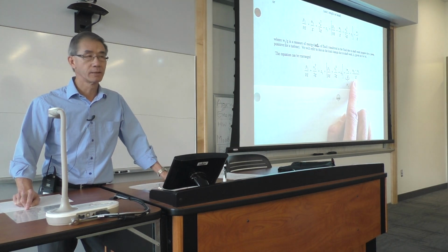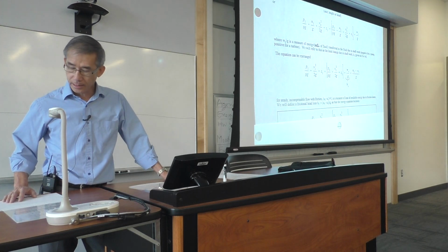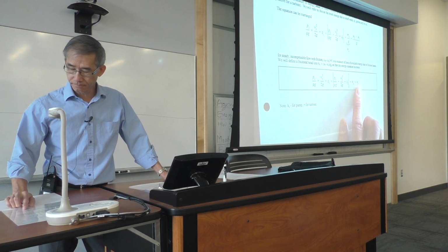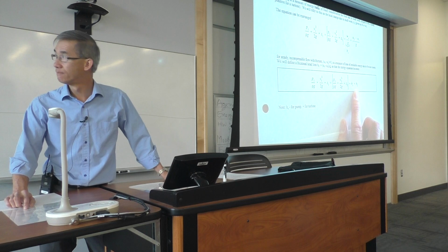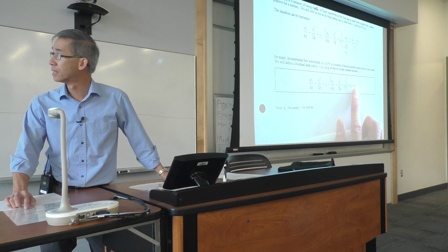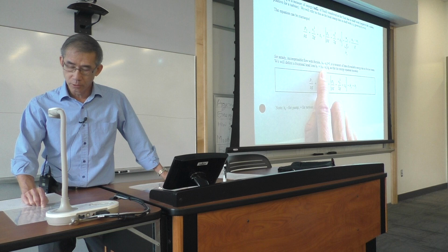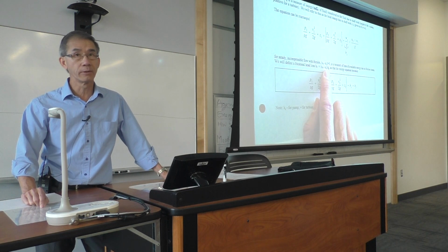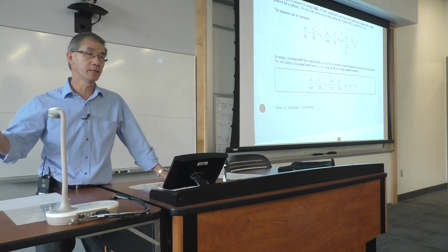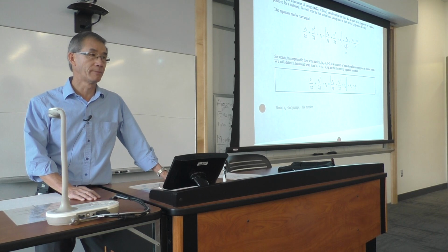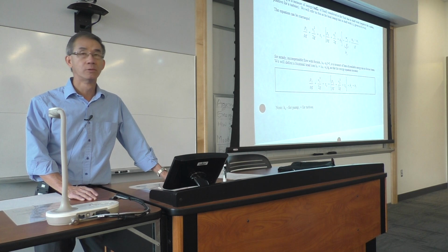U2 minus U1 divided by g. That is now the punchline. H sub F is nothing but U2 minus U1, the exit internal energy minus the inlet internal energy, divided by gravity. For an ideal gas, how do you approximate the internal energy U? Cv delta T, very good.